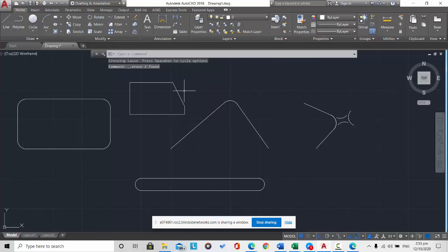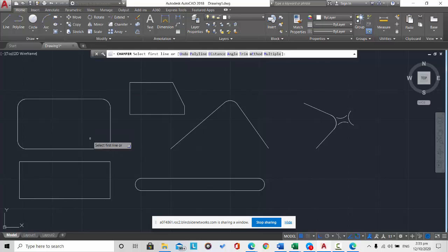Now, the explanation of the 1, 2 in the chamfer, no? Earlier, we identified the measurements. So this is the 1. The measure of the 1 is here. That is the 1 unit chamfer distance here, and there are 2 units here, no? 2 units. So you can specify your chamfer distance. In this case, I'm creating another rectangle here, and I'm using the chamfer command again.